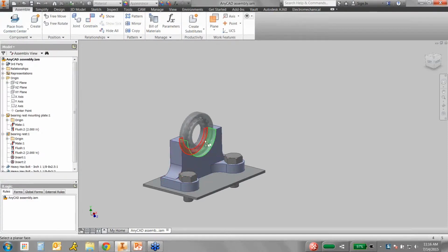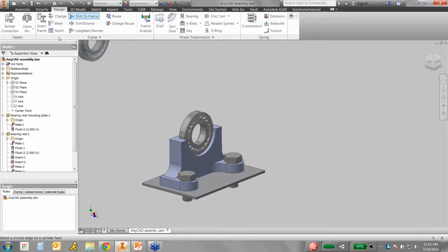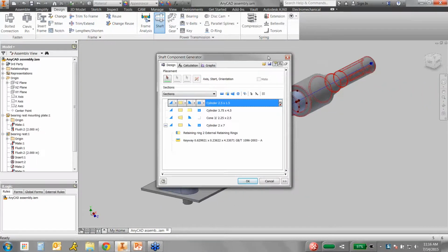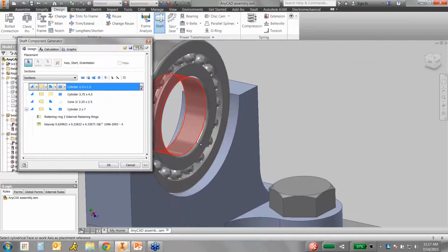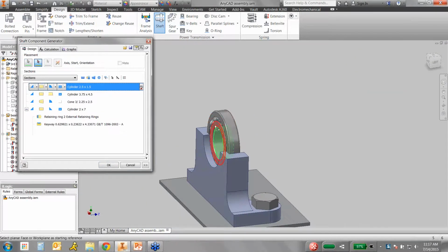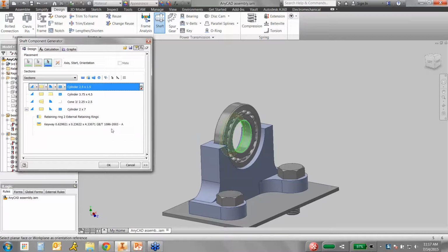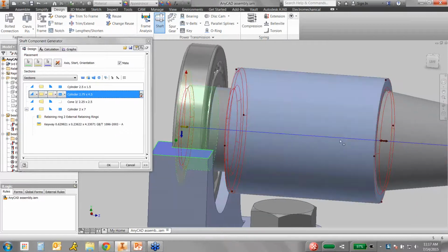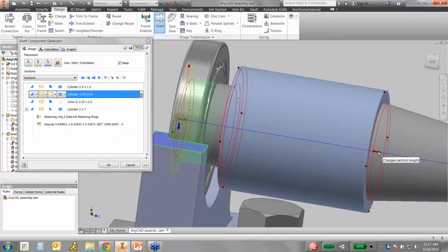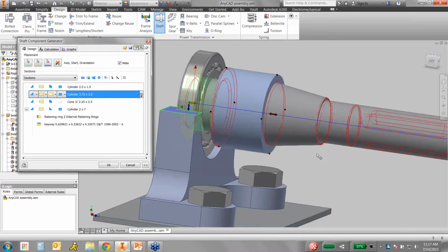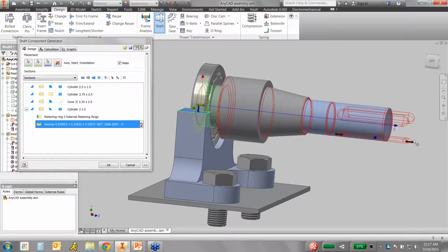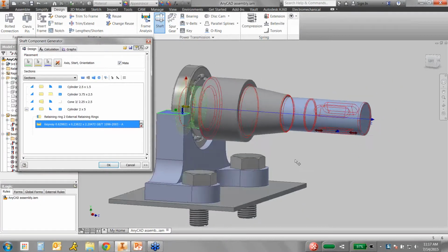So we'll just pick the location, and it'll generate the correct size. While I'm here, I'm also going to throw a little shaft in there in my design accelerator, so we have the shaft tool. And so let's go ahead and place that right in here. Pick an orientation. So if you're doing any kind of shaft design and you're not using this tool, this is great also. Very quick designs for every segment. All right, looks good.